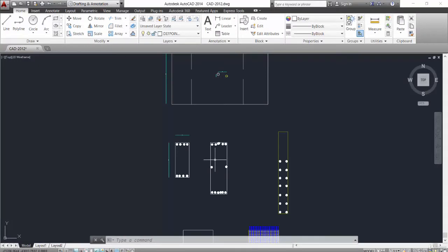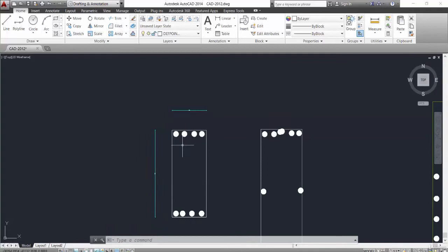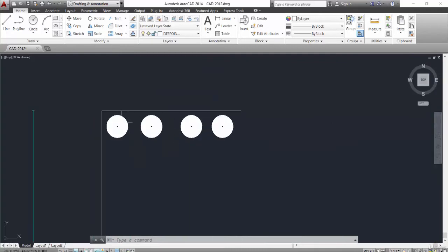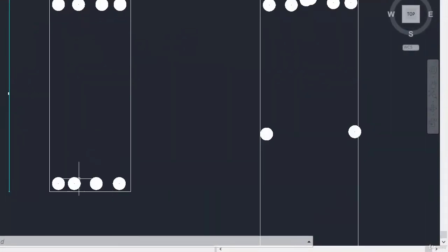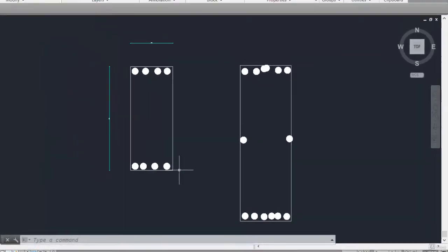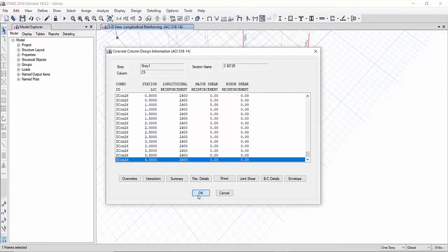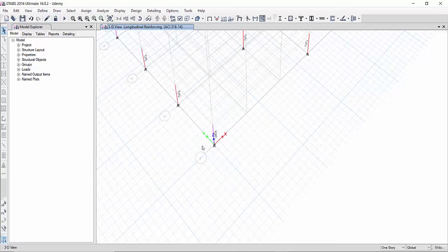So we go to the AutoCAD file, and we draw the column with the section equal to 800 by 300. We put here 6 rebars of 16 and 6 rebars of 16. This is just a shop drawing. We must draw the column with its section and put 6 rebars by 6 rebars to draw the shop drawing of this column. This is for the corner columns. So we see that the section 800 by 300 is the best section for the corner columns.